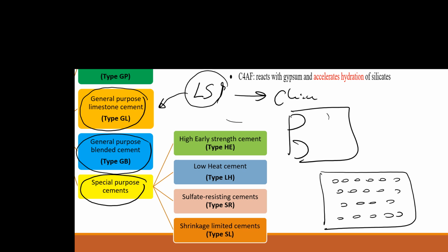Why is that? Water trapped inside the concrete, when it is getting like in the cold environment, it is becoming ice. So ice has more volume than water, isn't it? Am I right? Have you experienced that? If you fill a water bottle and put it in the freezer, the lid will come out, or else it will pop up, because when the water becomes ice it expands. The volume of ice is more than the volume of water.